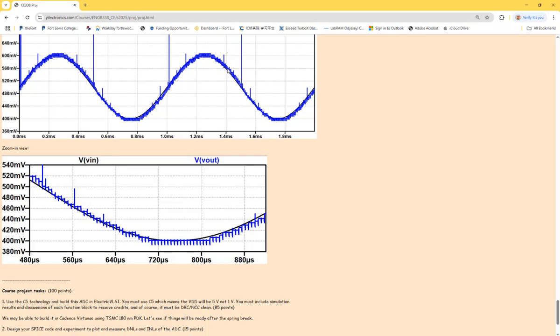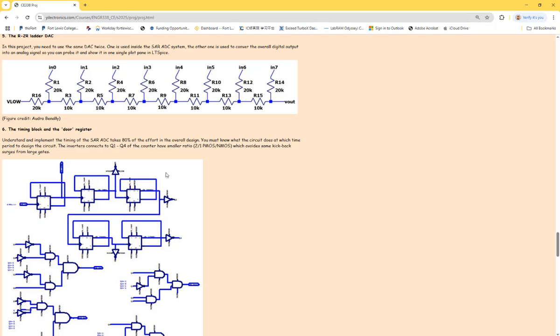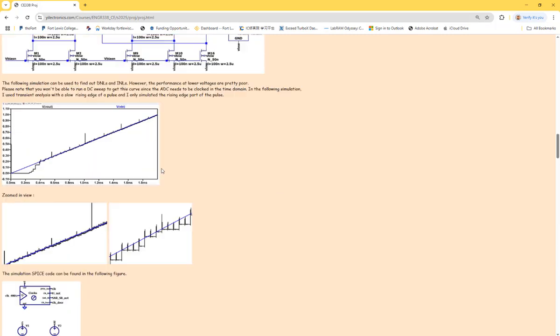So eventually, because the ADC's output should be 8 bits of digital signals, right? You couldn't see it clearly compared to the analog signal. So you have to run it through the DAC. So eventually, the output from the second DAC looks like this. You can see all these little stairs. And the thing is, I want to see the standard ADC curve to evaluate the quality of it.